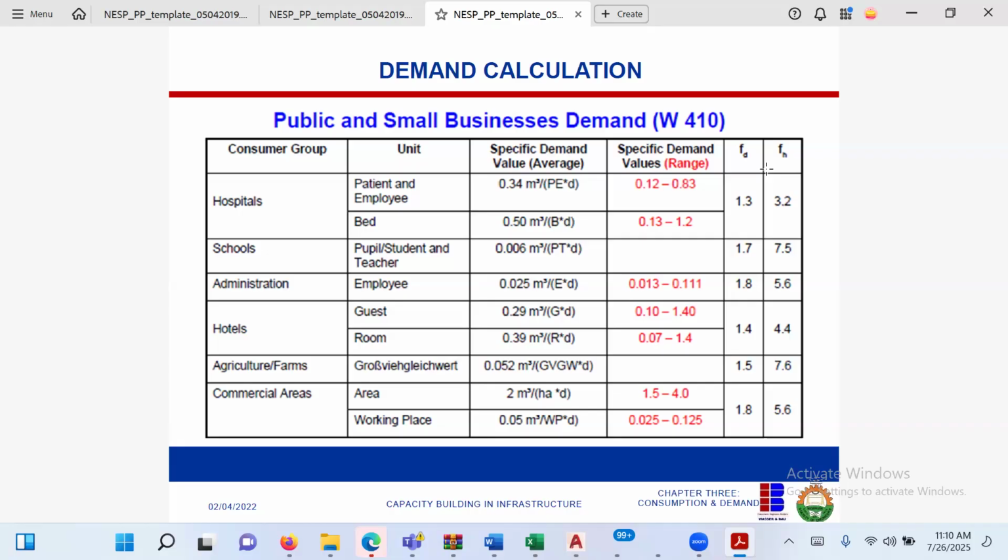If you get it wrong, every other thing goes wrong. It's the key major design. In fact, if you get your primary pipe right, you don't need to worry about secondary and tertiary. Because if there's an error in those ones, other areas will work. But the primary pipe, if you under-design it, you have an issue. Water will not even flow. And it can be very catastrophic.